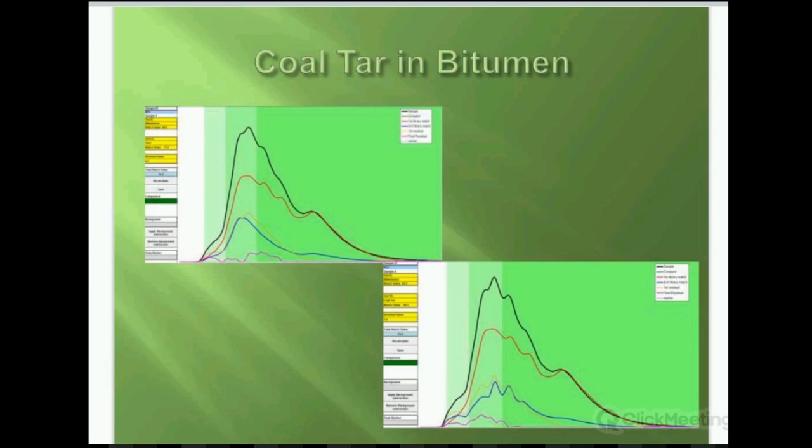And this sort of gives an indication of how it does it. So there's a fingerprint, the top one's the black line on that top fingerprint. You can see the red line of the first match, which is the bituminous material. And this bituminous material, our reference standard, comes from a certified reference material of raw bitumen. It subsequently goes in to make road tar, or the bitumen road tar. And the blue line underneath is the formulated standard road tar material, and you can see that that is the closest match. That's why this sample is identified as standard bituminous-based road tar.